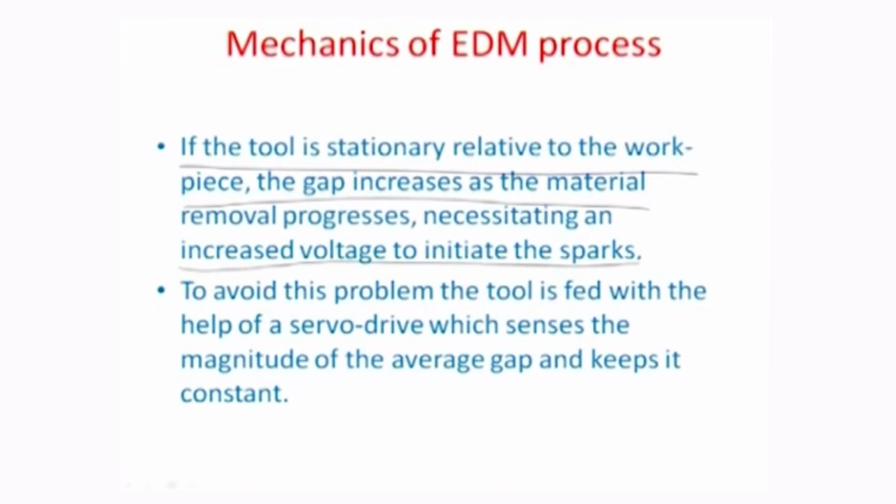is to operate on the distance of separation between both the electrodes by moving the tool closer to the workpiece. So if you have a situation where the tool is going closer to the workpiece, then also the distance d would decrease, and because of that the field would again be higher at a constant voltage value.